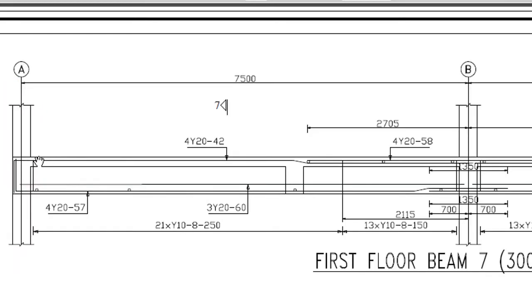So look at this first line here as well. It is a concrete boundary. They are telling you that it is a concrete. This second line, that's where the steel starts from. So definitely between this first steel and this first line, which is the concrete, there should be a cover. That's why you are seeing a space. That's the cover between this first one and the concrete. So all these external lines, they are what? They are concrete.